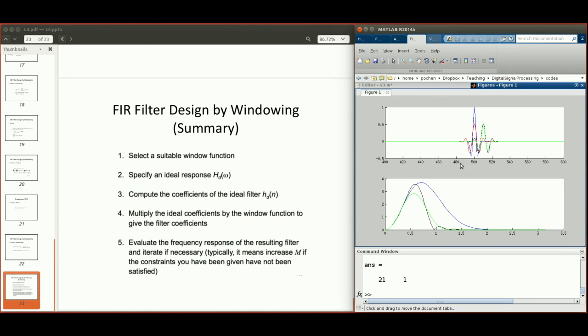That's our green curve, basically. So again, it's causal. In the time domain, you can see you have a constant phase shift, but the shape is still symmetric. And if you want to see some more details, you can blow up this segment. The reason it's different from the black curve is because the filter is different, and you can see that from the frequency domain representation. You can see fewer ripples, a smaller amount of ripples, but the transition band is wider. That's one of the trade-offs that you have to make.